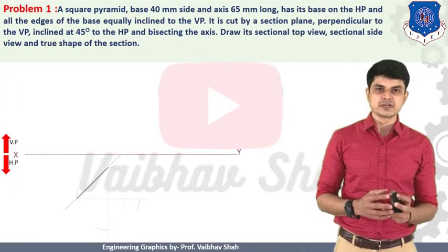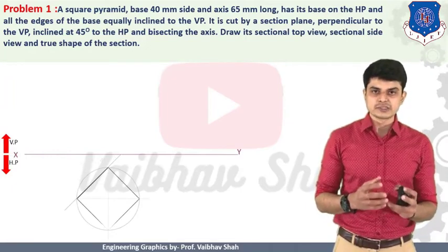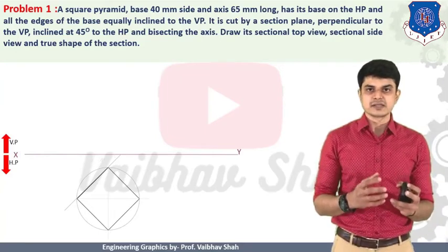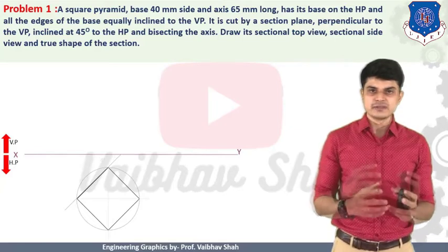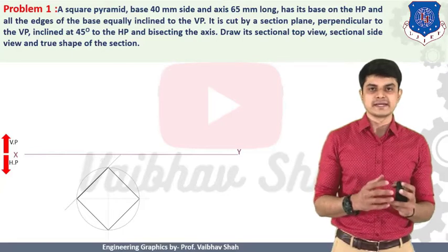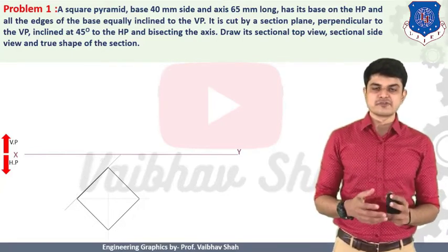So you will have one circle generated. After having this circle, you should draw your square by just extending the lines until the circle's end point. So this is how we can generate our square which has all of its sides equally inclined to your vertical plane. Right? Thereafter let us draw the diagonal points of your square like this.